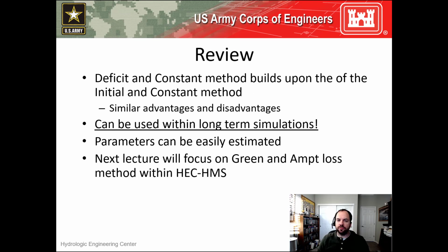In this video, I introduced the deficit and constant infiltration method, which really is a great option to become familiar with. This is a really good one for simulating infiltration, and in fact, I use it all the time on studies myself. It's quick to parameterize and calibrate, and it allows for continuous simulation. In the next video, we're going to focus on the Green and Ampt loss method, which is a more physically based option and includes a few more dials to use when calibrating.